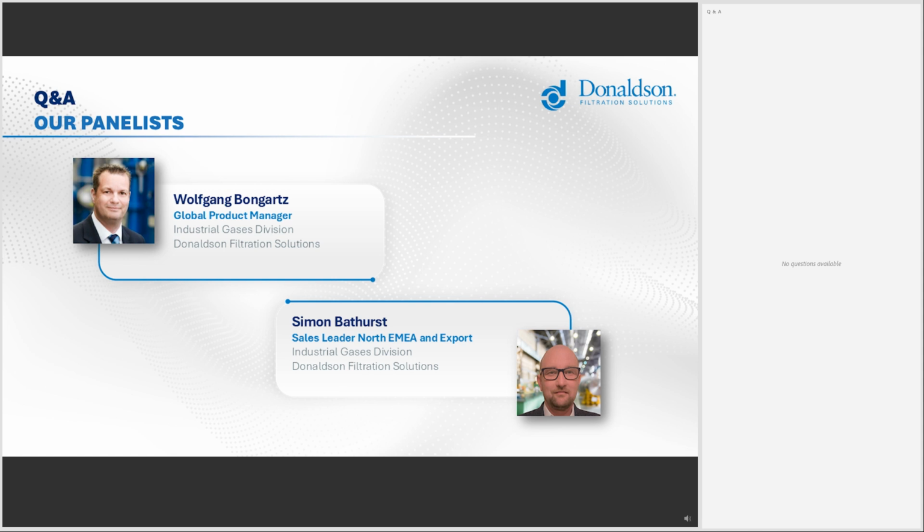But there are many other applications which require the low pressure dew points, in critical applications. So everywhere where you need to, for instance, also to avoid freezing of the compressed air, where there's a risk that the temperature falls below 0 degrees Celsius, it's also recommended to use desiccant dryers. Thank you, Wolfgang.